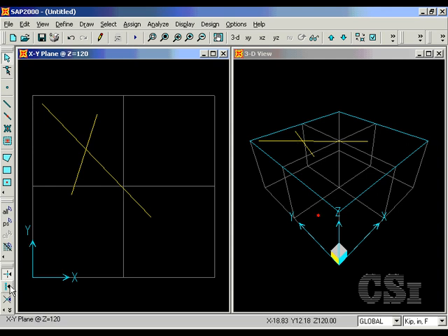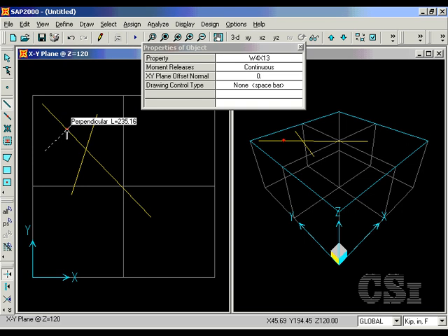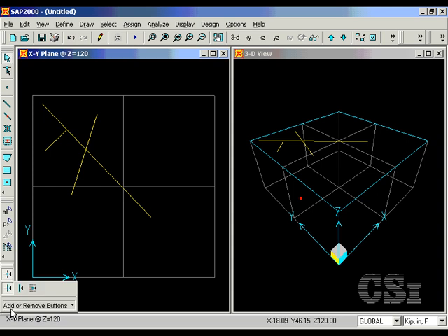However, there are many other Snap to options available, including Snap to Line Ends and Midpoints, Snap to Line Intersections, Snap to Perpendicular Projections, whereby a line can be drawn perpendicular to any existing line, and Snap to Line or Edges. This concludes this tutorial.